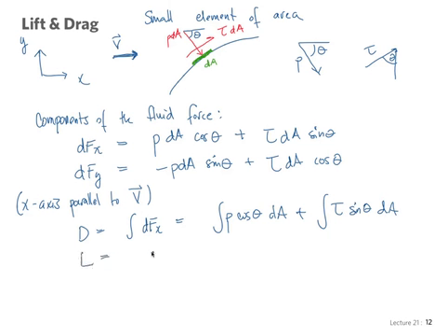The lift is the integral of the vertical force, and that's minus integral of P sine theta dA plus integral of tau cosine theta dA.